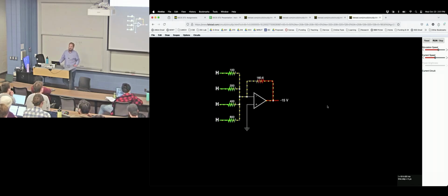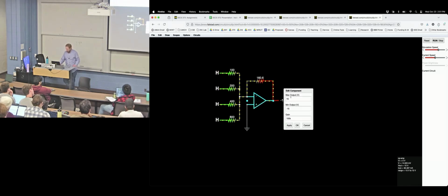If the inputs are 5 volts, how does it go to 15? So remember, there's gain associated with this. This resistor here is giving some gain to the signal. And this particular thing has negative and positive rails for the op amp, right? So in this case, let's look inside. The max voltage for VN is 15 and negative 15. Does that answer your question?